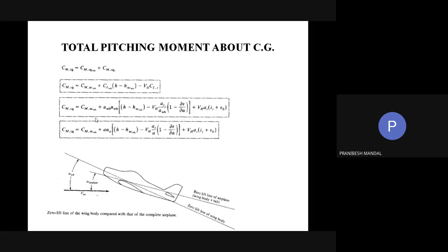It was shown that the moment coefficient about the aerodynamic center is negative. Yes, sir. So this term is negative. Right. So what is the next term for CM0? This one. Yes, sir. So this term must overcome the first term in order to make CM0 positive. Obviously, sir.